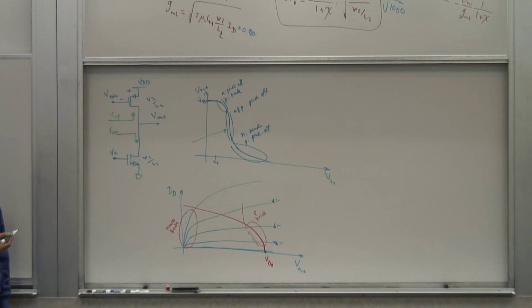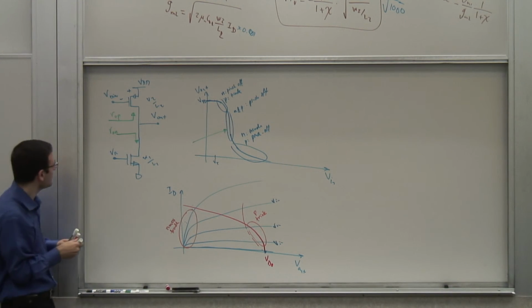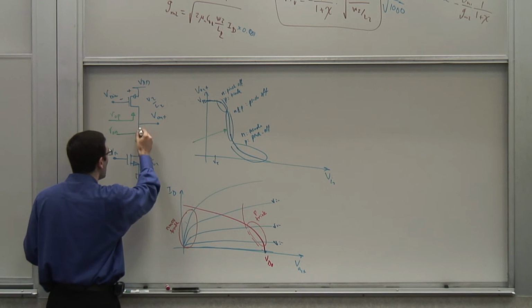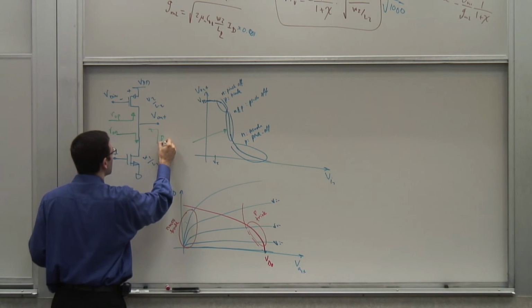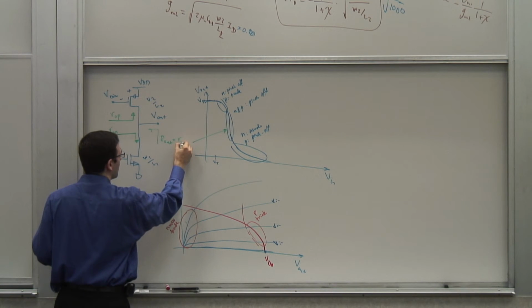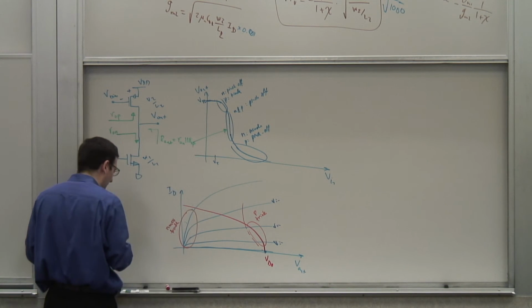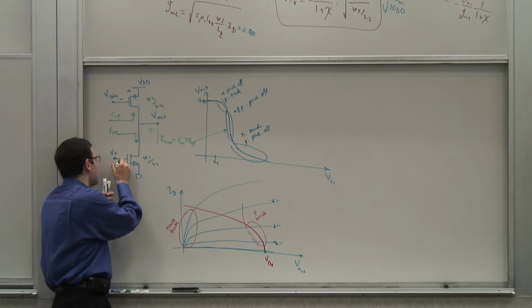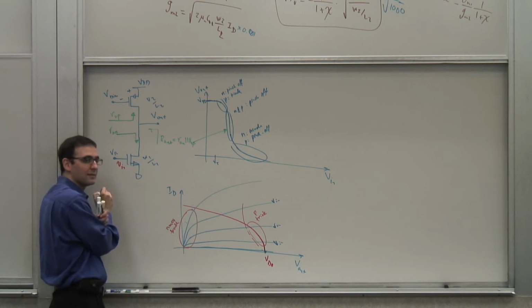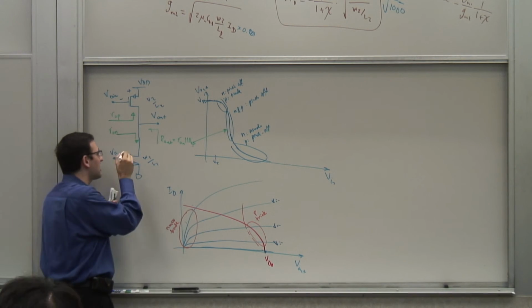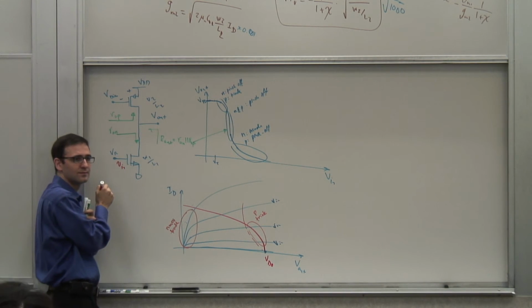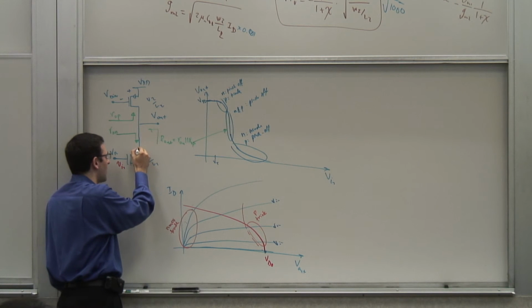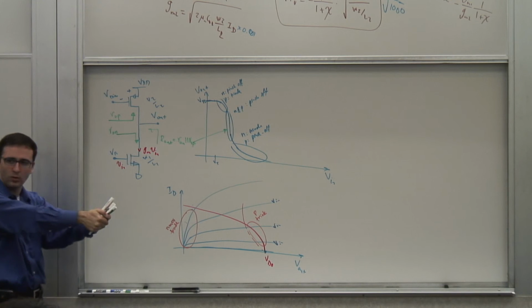You remember we did a similar thing with bipolars when we had the PNP and NPNs last time. So the total resistance on this node to ground, really Rout, which is the output resistance, is RON in parallel with ROP. Now, let's think about it, again without drawing a small signal model. If this voltage perturbation is vn, what is the current driving this node? The transconductance of this guy, right? The current is Gm vn. It's being pulled out of that node.